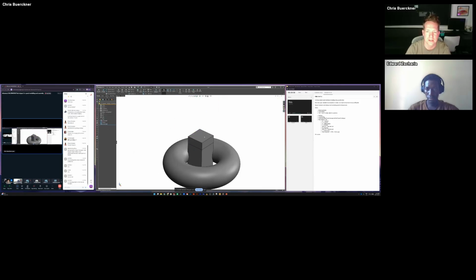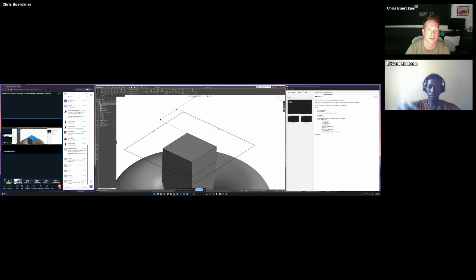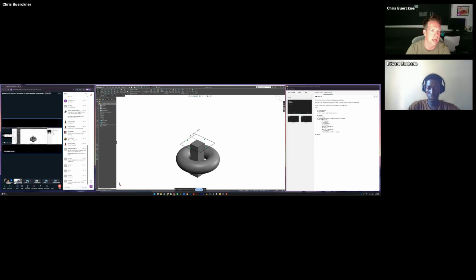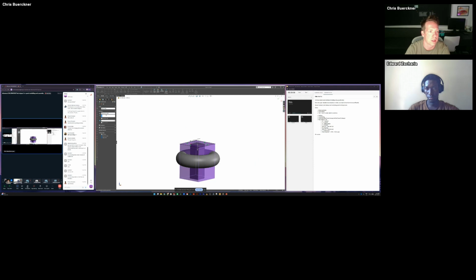I use offset sketch for a similar thing. So I use O for offset. All right. Again, quicker than having to navigate up here, or to press the S key and then try and find offset sketch here. Instead of pressing S key plus offset, I just press O, and it's a bit quicker. I've already mentioned the ones that I've done for extrude. I should also mention I've done the opposite for cut extrude. So cut extrude becomes Shift plus E, all right, to remove everything.